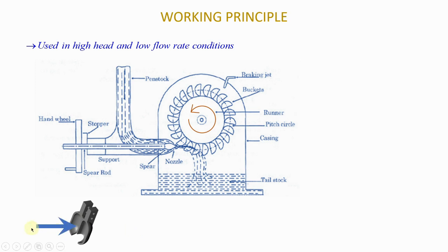So as the jet comes in this direction, because of the split that you see here, the jet will be divided, and some of it will go that way and the other portion will come in this direction. So if you look at the somewhat top view of the bucket, which is what you see here, and you have the jet of water that is coming, which we refer to as the incident jet. And so this jet is coming with a velocity vi, and then it interacts with the bucket.